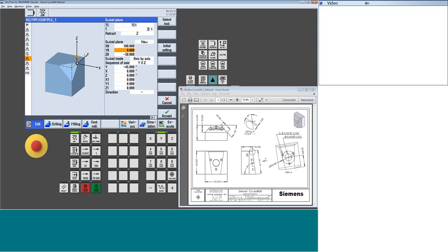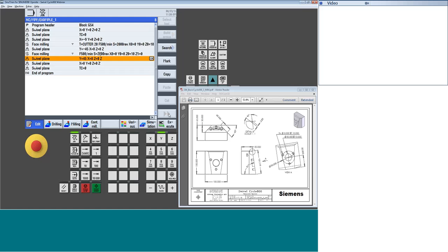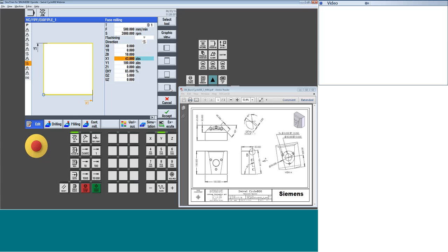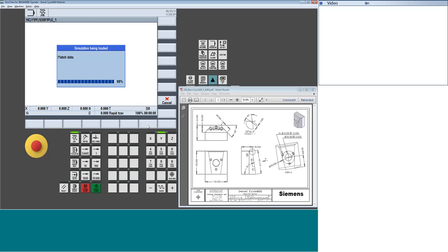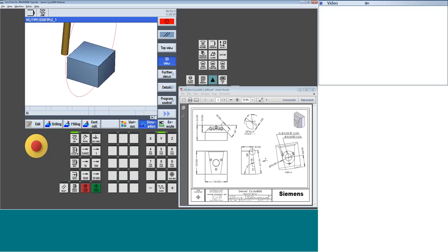In this case, I'm going to be rotating right from that point, that negative 30, and I'm going to be doing the opposite, so a positive 45. So now all of my stock exists in a negative in X. So if I grab the swivel cycle, or shall I say the face cycle, paste it, and just merely change my direction to negative 43, we now start to see machine to 45, machine to next.